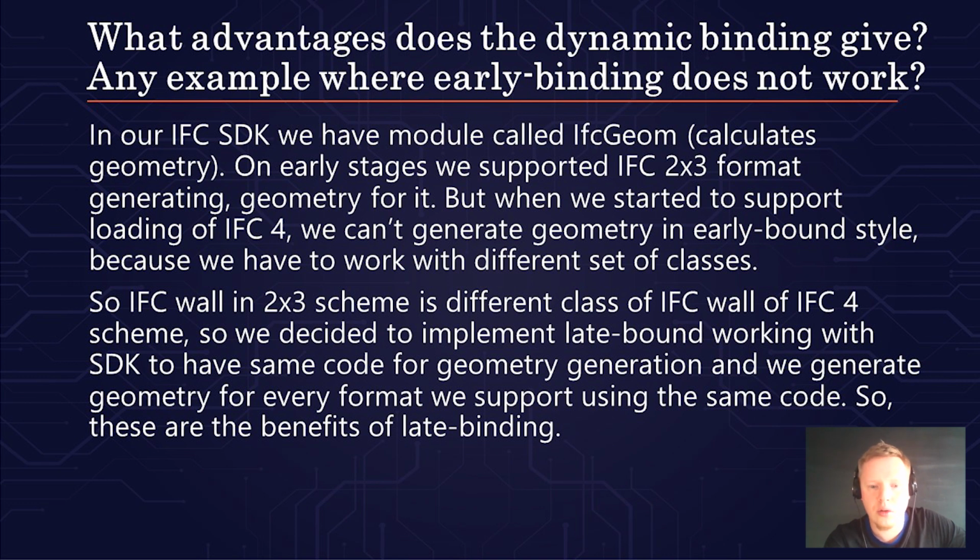In early stages of implementation we were supporting the IFC 2x3 format and generating geometry for it, but as soon as we started to support loading of IFC4, we could not generate geometry in early bound style because we had to work with a different set of classes. So IFC wall in the 2x3 schema is a different class from IFC wall of the IFC4 schema.